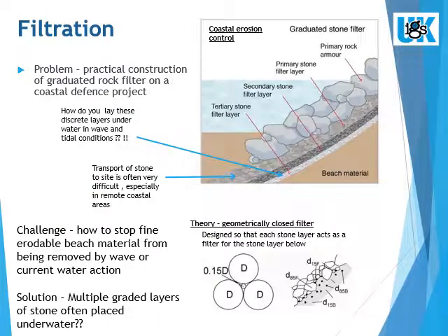Typically, rock armour is used where embankments to rivers and coastal areas are subject to wind-blown waves or heavy flows which, if untreated, will erode away. Fine sands are particularly erodible, so weighting it down with heavy rocks which also break up the waves is a good solution in sensitive areas. The problem is the gaps between the rocks, and when the waves or flow of water occurs, the subsoil is sucked through the gaps between the rocks.